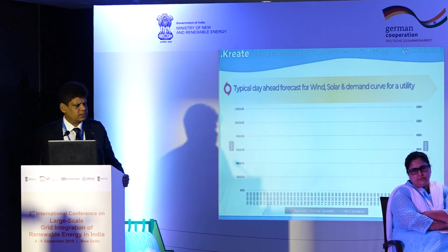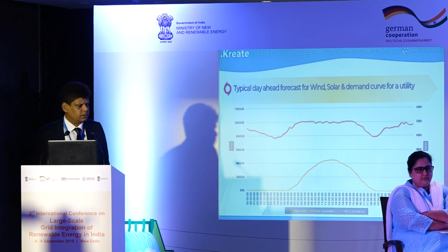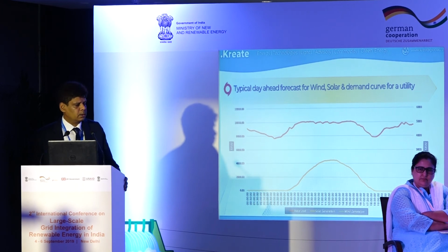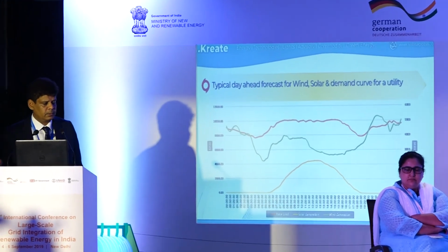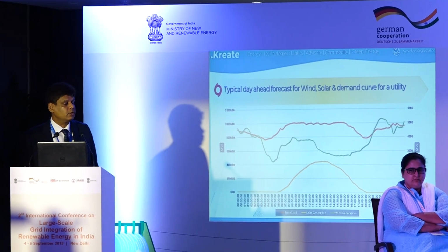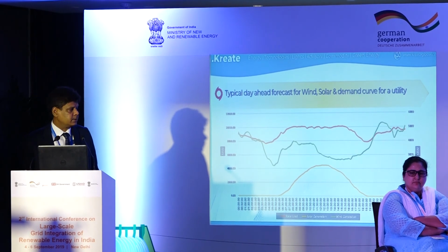And just to give you a sense of the load curve, this is the state of Rajasthan, not mentioned here, but this is one day's load curve for Rajasthan. This is how the load moves. And this is the integrated solar load, Rajasthan having around 2,000-odd megawatt of solar. This is the total solar curve for the day for the state. Mr. Kumar, sorry, 2 minutes more. Yes, sure. Thank you. I'll finish this. And this is the wind curve. The scale is different on the left-hand side and the right-hand side. So the wind curve and solar curve for the state and the load curve need not necessarily move in the same direction. They move in opposite directions, and you need to find a way to balance them.